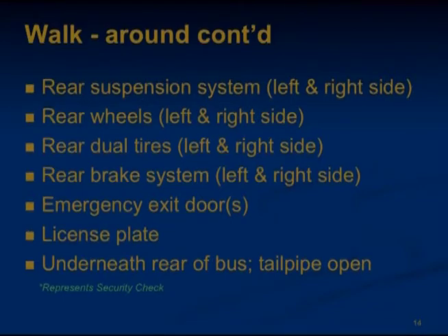Make sure that the frame is not damaged, that the spring hangers are secure, leaf springs are not shifted or broken, and that the axle, shocks, and mounts are not broken or leaking. Rear wheels and wells, make sure that there's no excessive corrosion, cracks, or other damage. Make sure that the rims are not damaged and have no welding repairs, that the lock rings are secure, and the lug nuts are tight and not missing. Make sure the spacers, if they're equipped, are not bent, damaged, or rusted through.